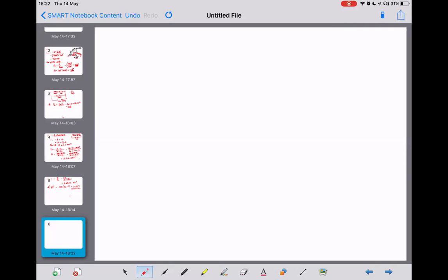Well, RMS involves root 2. Line and phase voltages and currents involve root 3. The way I remember line and phase is that in star, your line voltage between two lines, 400 volts on our mains, is bigger than your phase voltage. So you must divide the line voltage by root 3 to make the phase voltage smaller.